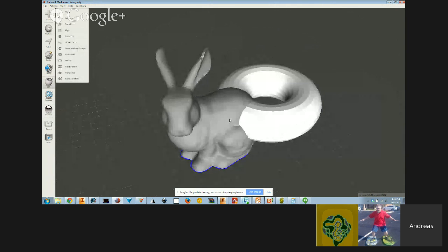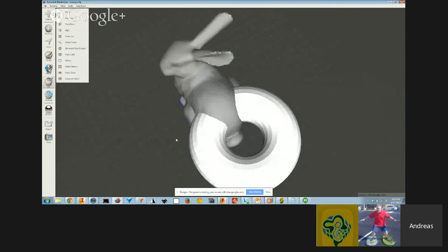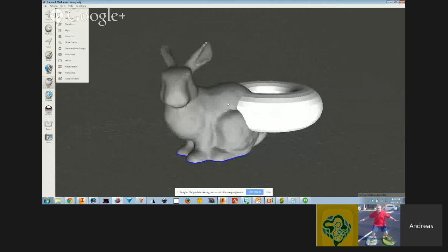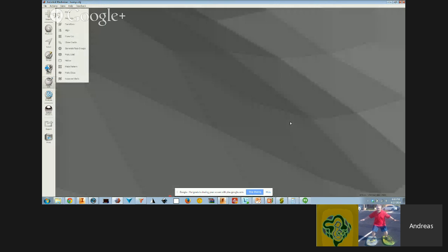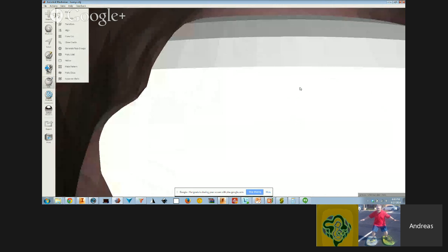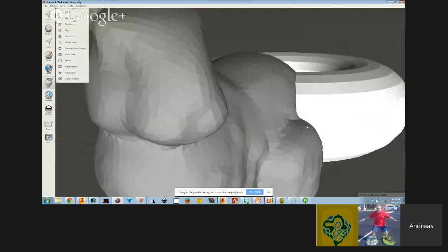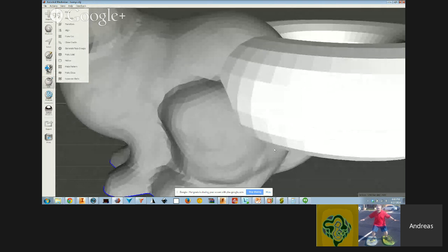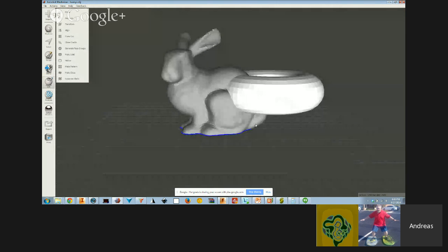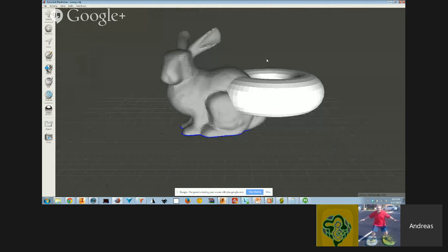Let's say I wanted to 3D print this. That's kind of like a pencil topper. Well, I don't know what the heck it is. I have mesh issues. If I look on the inside of it, I have this whole thing going through it. So I have self-intersections here, and I have a big opening here. So what I would do is a make solid in this situation.